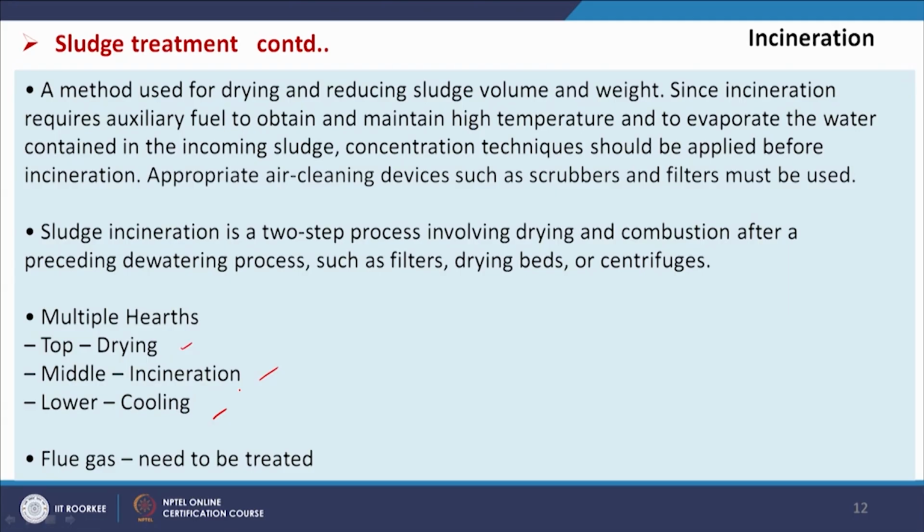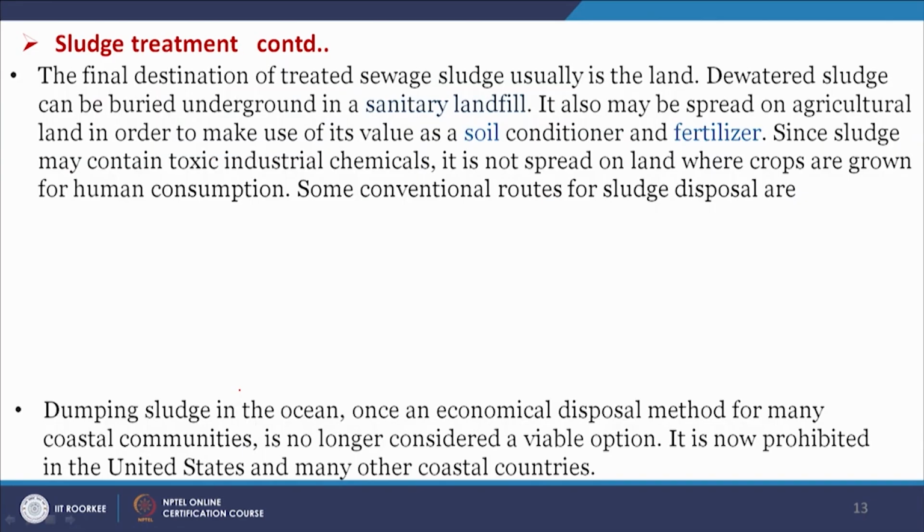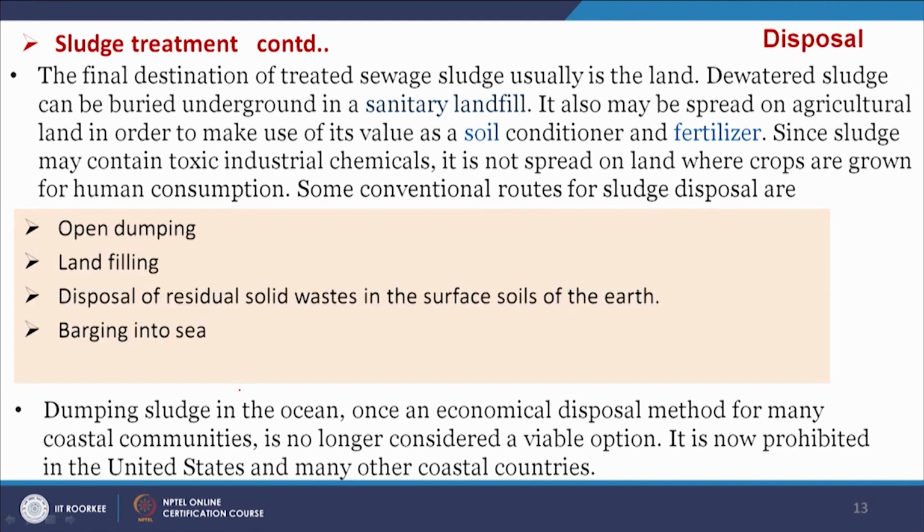So, this is the incineration, and we will be having a detailed discussion on incineration in solid waste management, and the same methods are applicable for the incineration of sludge also. Now, we are coming to the disposal part. The final destination of treated sludge usually is the land.